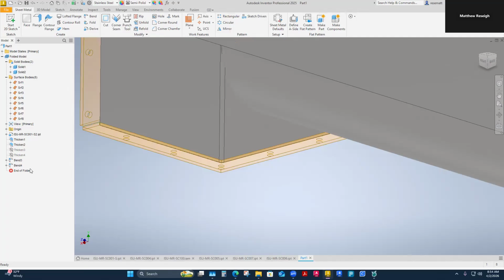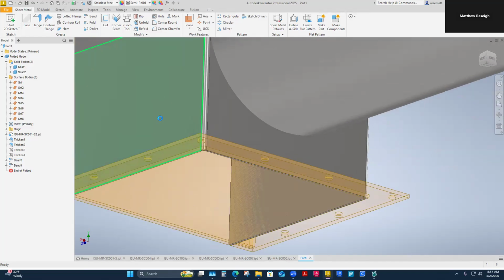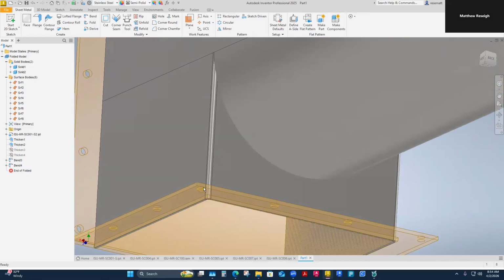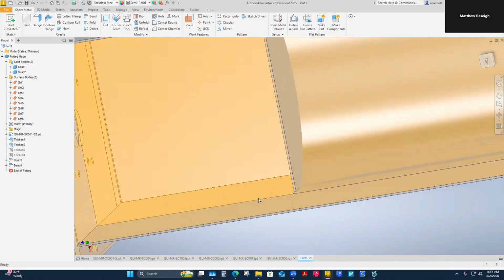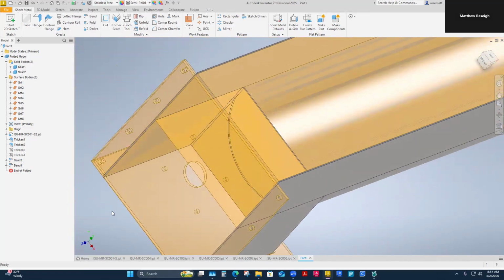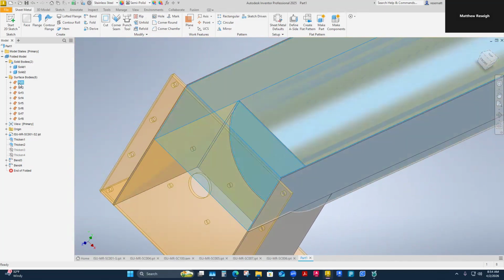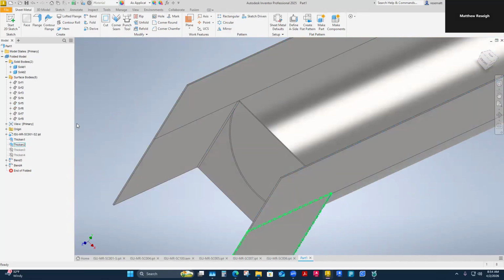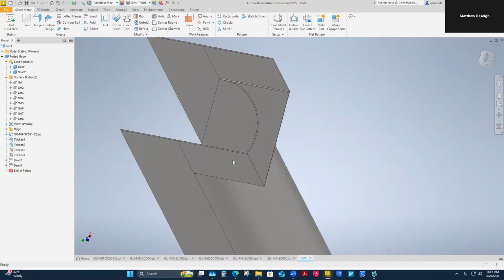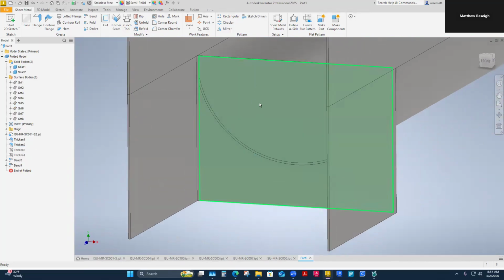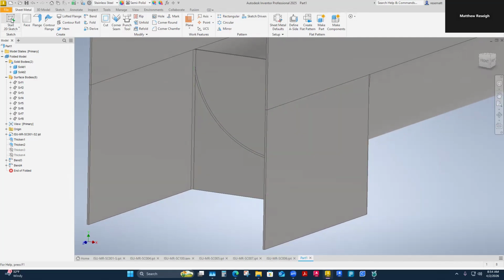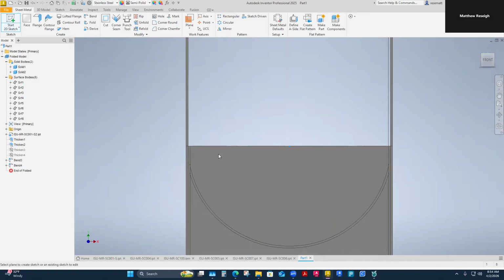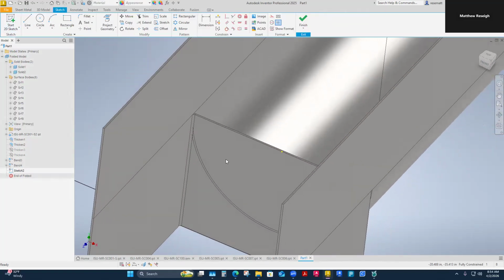I did new bends. Yep. Once I thickened those sides, I made new bends, and that's what I've got there. Now I've got to make a new sketch to cut that back out. So let me do that. For me, I've got to turn off my surfaces, turn the visibility off. And so I'm actually choosing that original cut sketch I think we drew here as well. I'm going right back to that and saying, let's use that surface as my sketch surface.